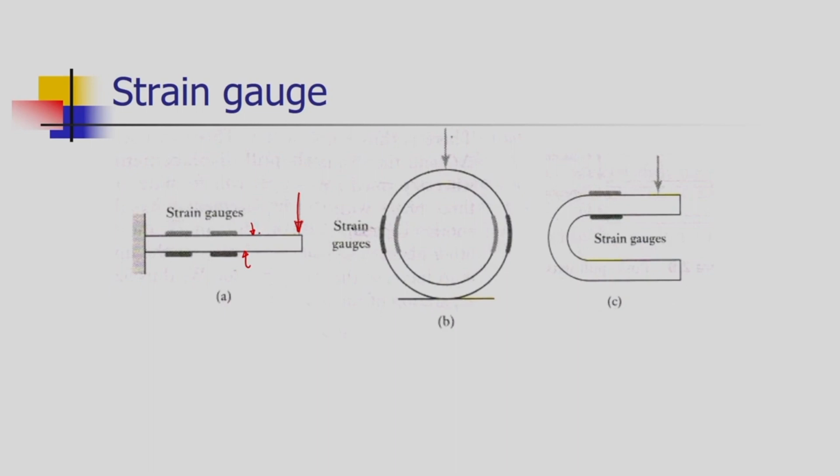So, we are getting an increase in resistance values of the top strain gauges and a decrease in the resistance values of the bottom strain gauges. By measuring the periodicity of the signals we get from the strain gauges for this increase and decrease, we can easily monitor, record or measure the vibrations value.